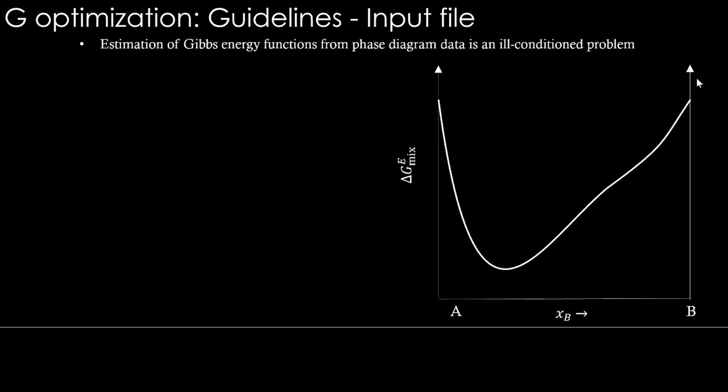Okay. And let's bring another phase like this. If two phases are to be in equilibrium, this is the common tangent, and these are the points we get as tie-line information from this. Okay, so let's say this information is available. This tie-line information is the phase equilibria data, right? This is available to us, and from this we want to reverse and come to this kind of Gibbs energy curves. Okay, so that is what Gibbs energy fitting from phase equilibria data is.